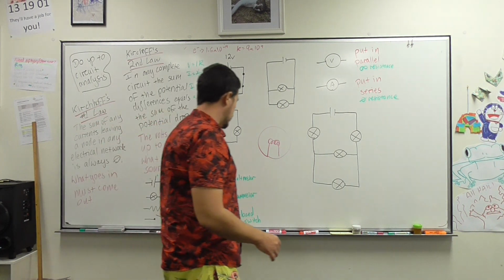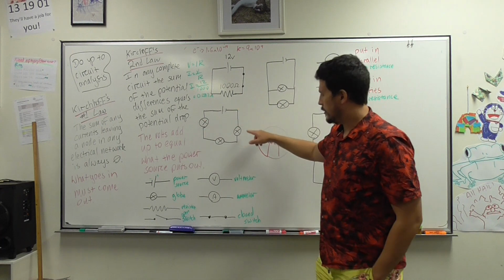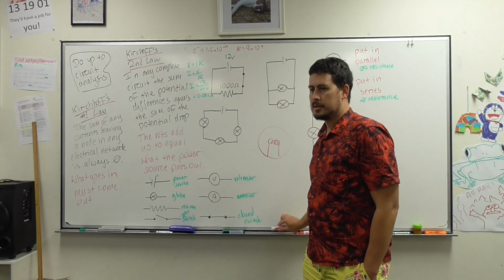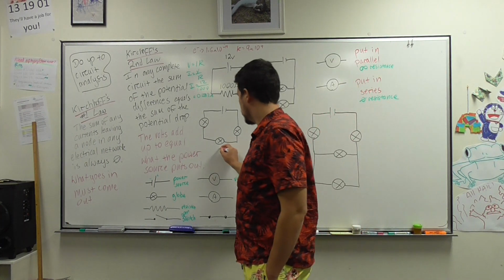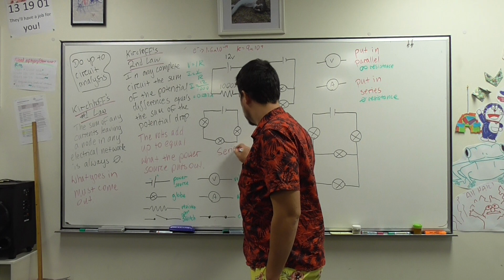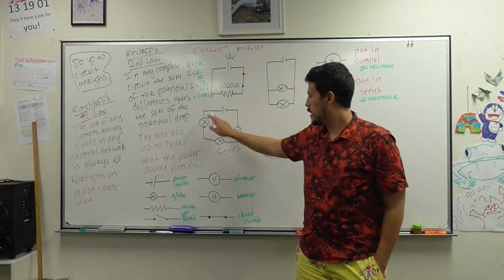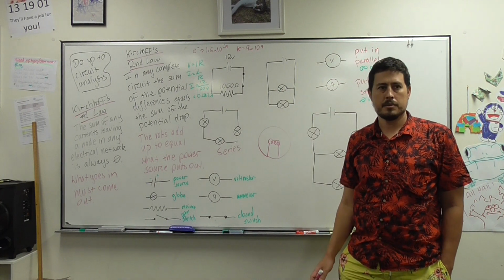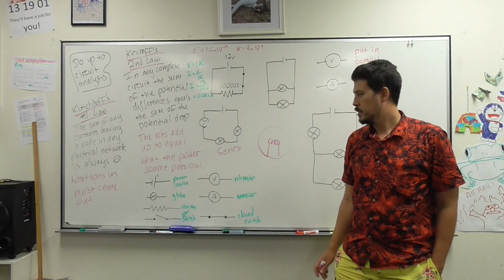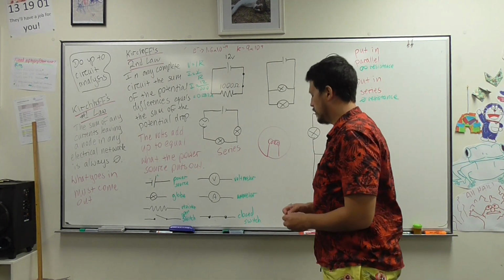Now, in any circuit where the things are put around in the one path that it can follow, what do we call that? What kind of circuit is that? So that's with the letter S. Series. A series circuit only has one path, so the electrons can go around that way. If one of those globes blows, you've cut the circuit. The electricity won't flow. So a series circuit has everything in one path.